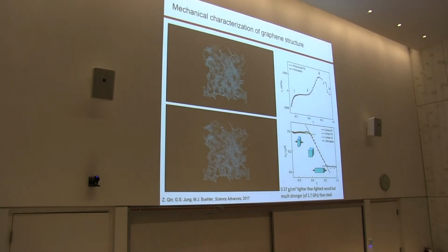I can use MD simulation to simulate tension loading and compression loading on the material, and get a full stress-strain curve for this bulk material from compression to tension. I can get the strength of the material, and also the Young's modulus and Poisson ratio. In the simulation, you can clearly see how those covalent bonds contribute to the strength, the stiffening behavior, and the large extensibility of the material.